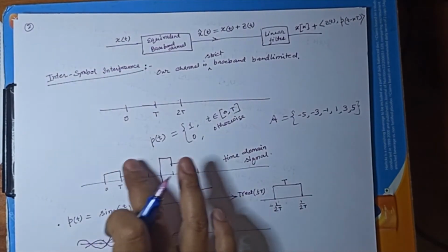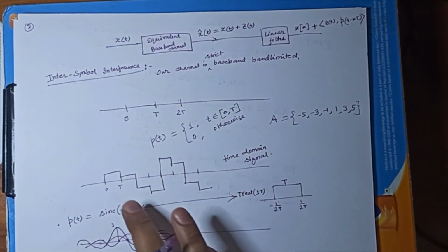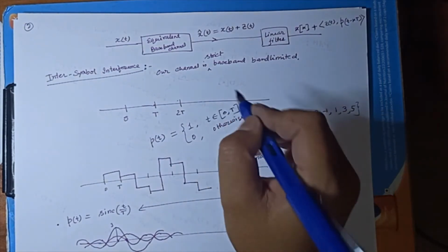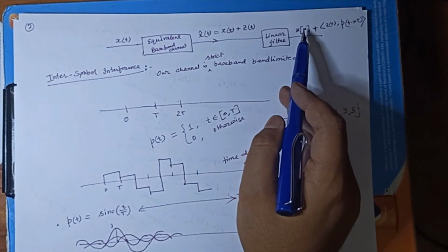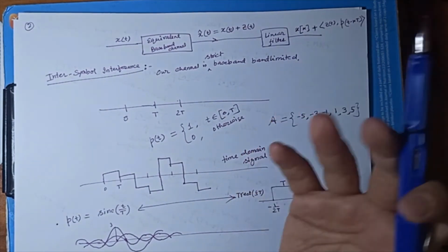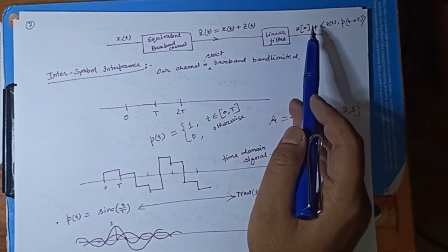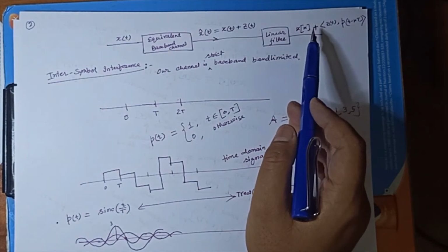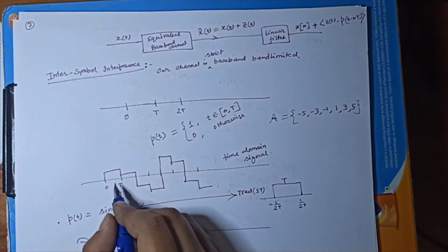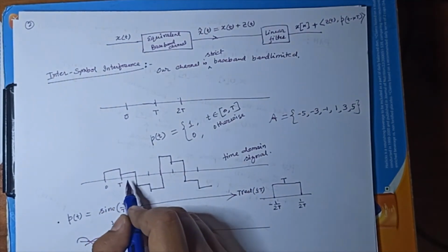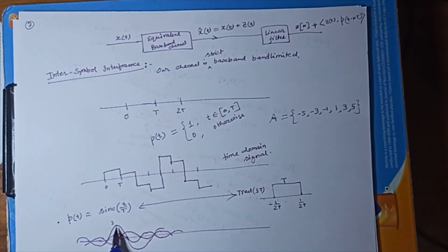So when I have drawn a signaling like the rectangular or the sinc, we see one thing for sure, that to get back the digital, like discrete time signal, the symbol, you have to do sampling, because this is essentially uniform sampling. Okay. So for this, the sampling can be anywhere between kT and (k+1)T. For sinc, it has to be exact. So a sampling block will be there.